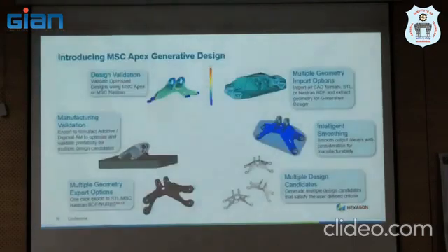Okay. This is what we call the generative design cycle. When I say topology optimization or DFAM, before that we start with the initial understanding of the design and non-design space, in the sense of where the areas are in which I am not allowed to remove any material, because it might be fitting into another body, or we may have to integrate with the main system, or these might be load-bearing areas.